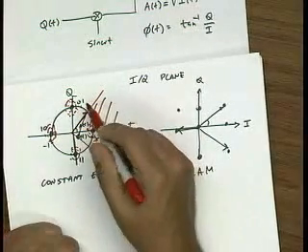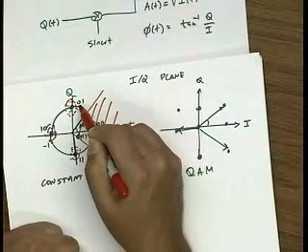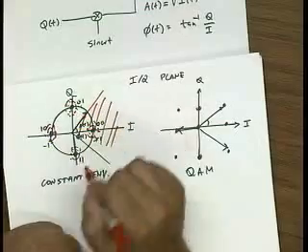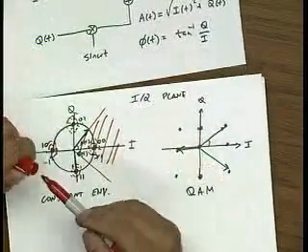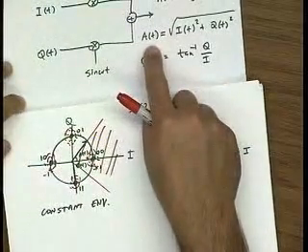If the noise is large enough that it moves you out of this quadrant, then you'll make an error when you're sending a 0, 0. In fact, you receive a 0, 1. So the space between these 2 points is very important. And remember, the space between these 2 points is related to this amplitude. And of course, that's related to the power of the signal.